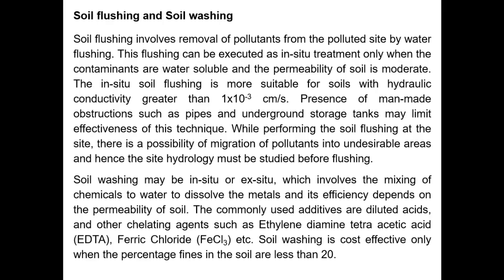Presence of man-made obstructions such as pipes and underground storage tanks may limit effectiveness of this technique. While performing the soil flushing at the site, there is a possibility of migration of pollutants into undesirable areas, and hence the site hydrology must be studied before flushing.